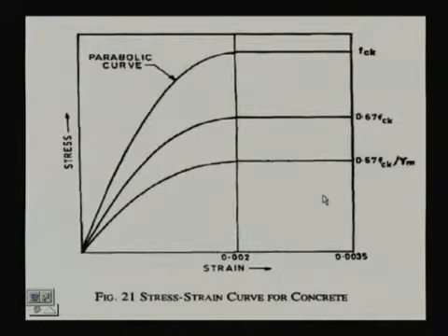For our design purposes, we are taking this curve, and when we take the actual value, the design value, we shall consider this curve, which is based on the curve we are getting from the experimental data. Then we are taking 2/3 of that, further dividing by the partial safety factor for materials, and then finally we shall get the curve for our design purpose.